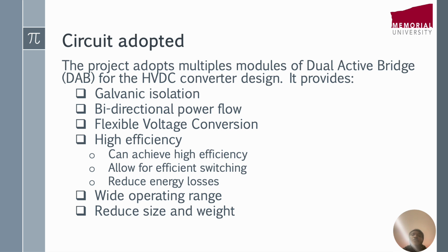Also, from our research, we realized that the dual active bridge is more efficient, and in terms of sizing, it is less bulky. And once the size reduces, it directly reduces our cost.